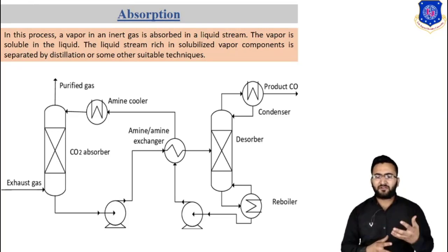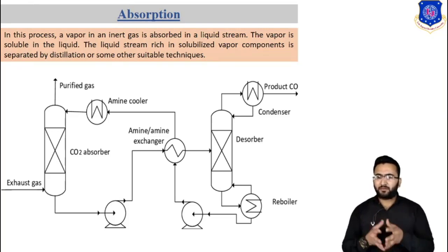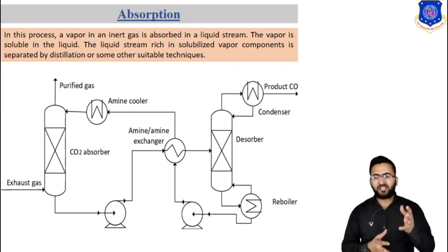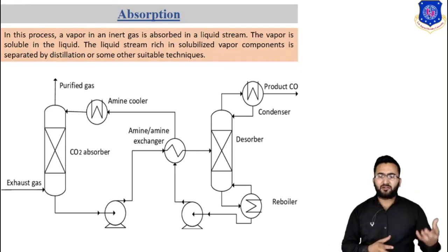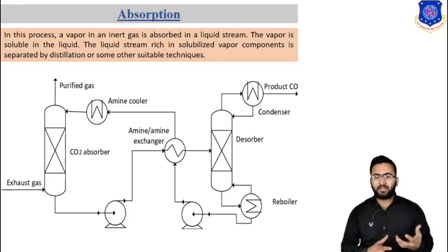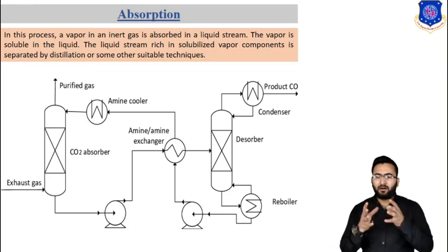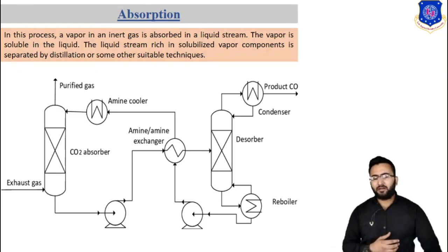To enhance the efficiency of this process, sometimes packed beds or staged beds like trays are used to have better mixing during the transfer process. It may be mentioned that absorption is a bulk phenomenon. The gaseous solutes are transported to the bulk liquid stream. It may be noted that to effect separation, a new material is introduced into the system. So this is all about the absorption process.